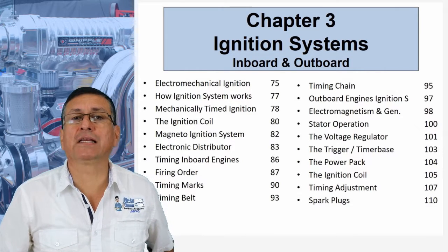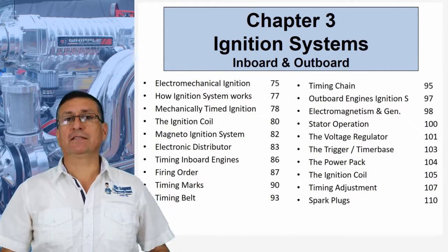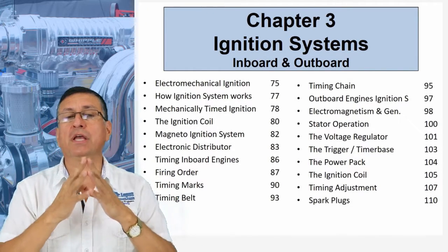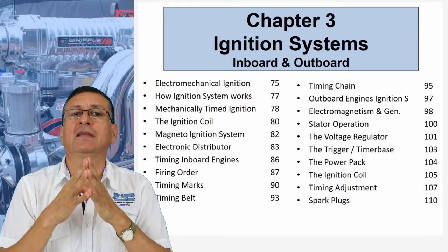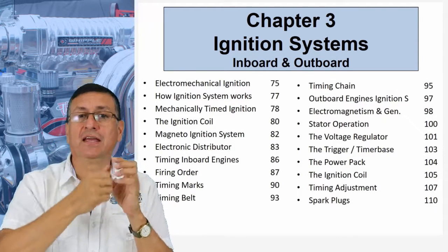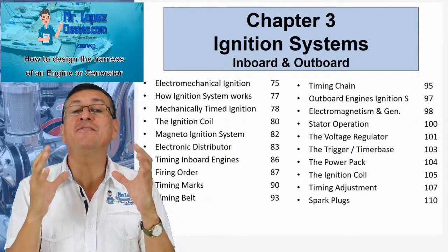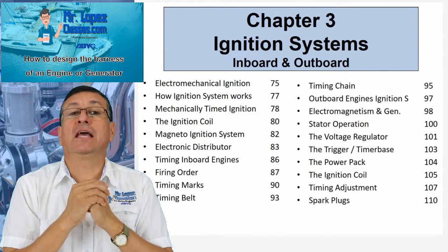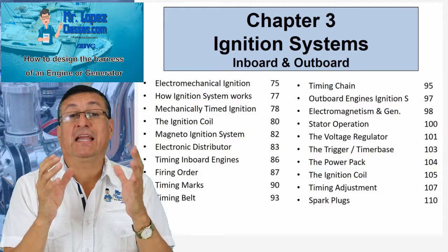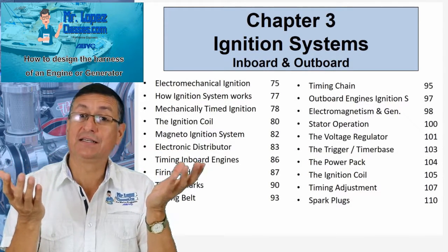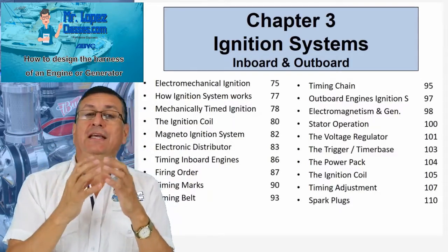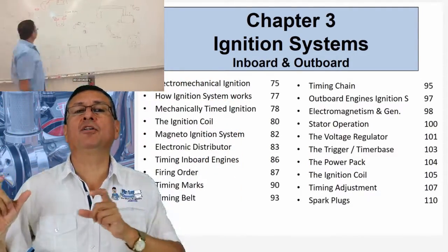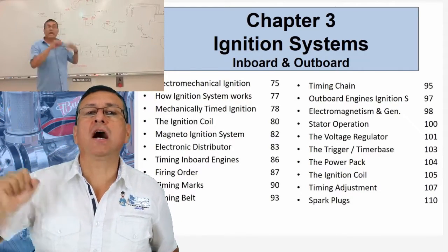Yes, you remember the alternator produces output power. What is the color of that cable? Orange. Exactly, the orange cable. That current coming out through the alternator goes into the run relay. You remember in chapter 15 of our electrical class, the episode related to the creation of the harness. In that episode, I explained how the harness is created and how the alternator is part of the harness.